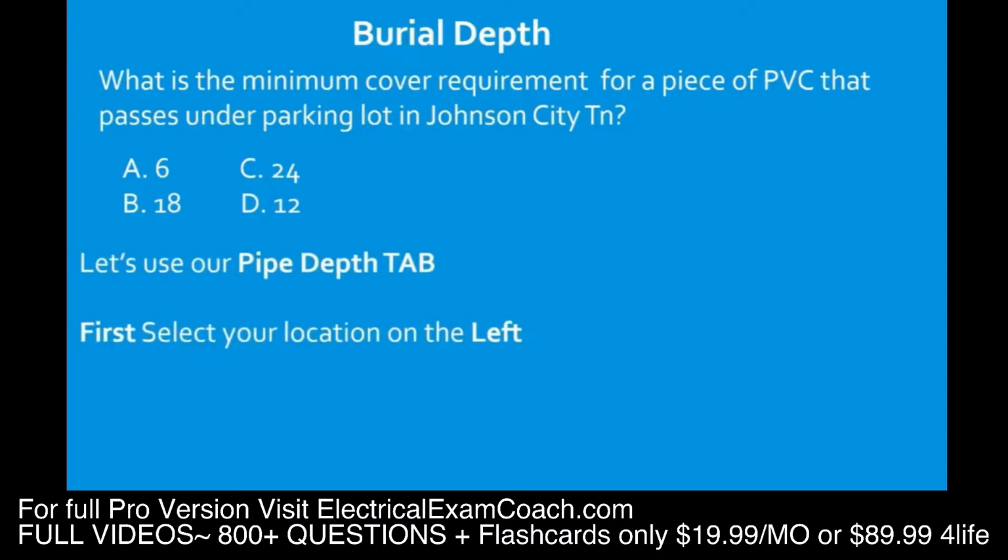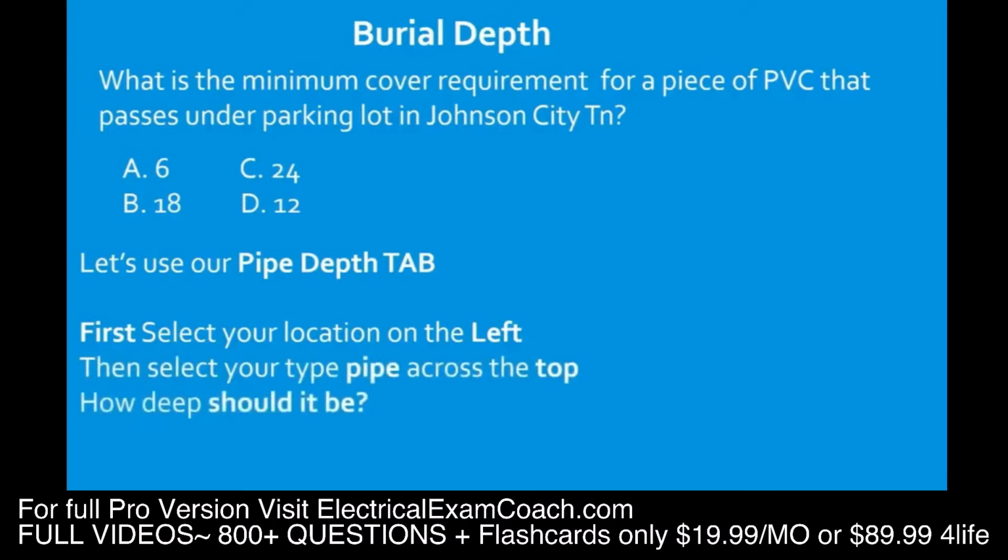Okay, and those driveways specified in this one are not your 1 and 2 family dwelling units that are down below. These are just general driveways going to other places. But in this case, we're going to use that one because it also lists parking lots. Then we come over and we tee off with non-metallic raceway, which is going to be our PVCs. And we're going to find that it is required to be not less than 24 inches. And we're going to select C.